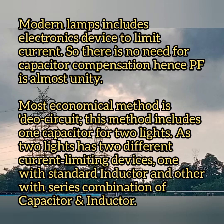Next, modern lamps include electronic devices to limit the current, so there is no need for capacitor compensation. Hence, the power factor of your modern lamps will be almost unity. Then, the most economical method is the duo circuit, which means a double circuit connected with one another. This method includes one capacitor for two lightings, as the two lights have two different current limiting devices, one with the standard inductor and the other with a series combination of your capacitor and inductor.